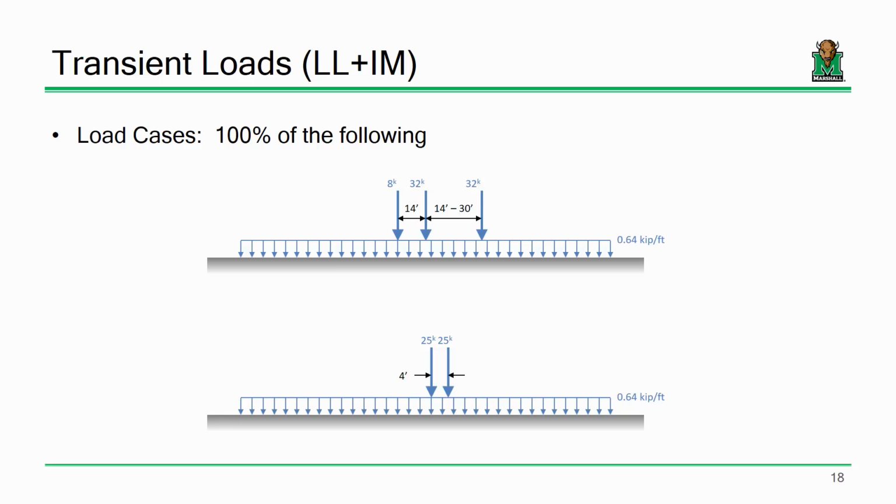Don't worry if it's been a while. We're going to cover it in detail. Okay, now that's the simple part. The axial spacing. If you're the engineer in charge of this project, would you put that axial spacing at 14 feet or 30 feet? 14. You want to lump those loads as close to the center as you can, right? Make sense? Okay, so yeah, it's variable spacing, but sometimes there's a little bit of logic that comes to that.